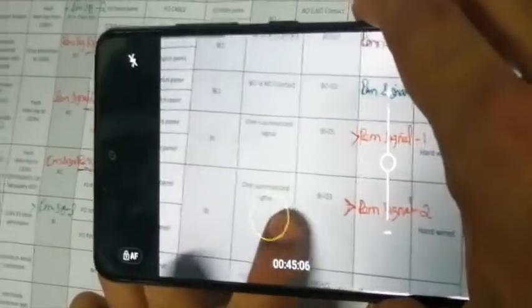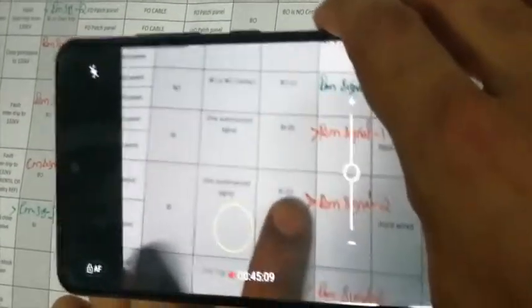The ABB relay provides one summarized signal on its output, which is the X110 card SO4 output. That signal goes to 11 kV Ciprotec relay binary input number 3, and from here the 11 kV Ciprotec relay sends this signal through a fiber optic link to the 132 kV Ciprotec relay. This signal will be generated at the 11 kV side from the ABB relay, and can be checked at the 132 kV Ciprotec relay on LED number 2. We have configured LED number 2 on the 132 kV